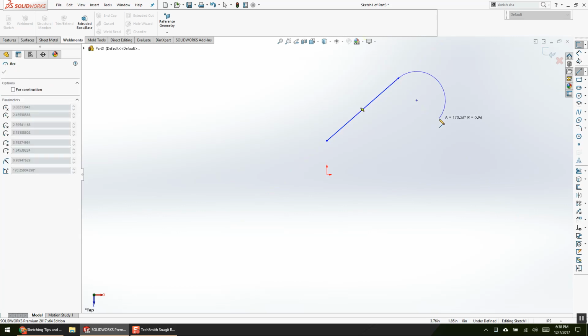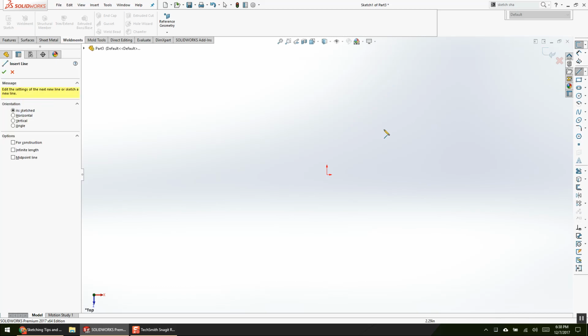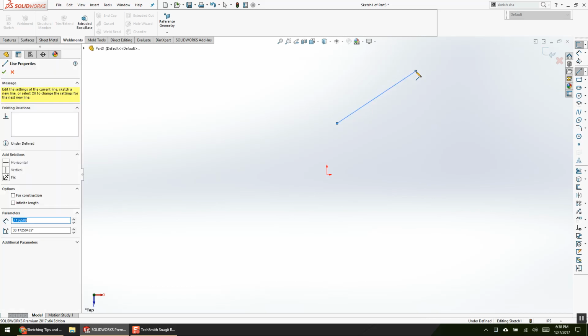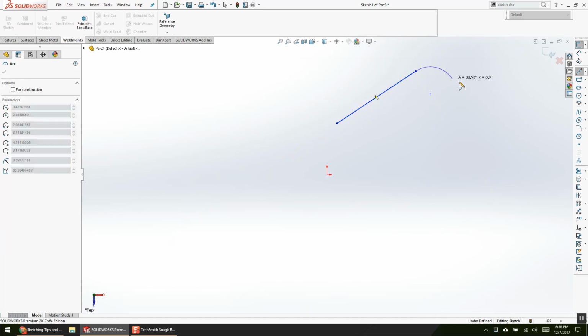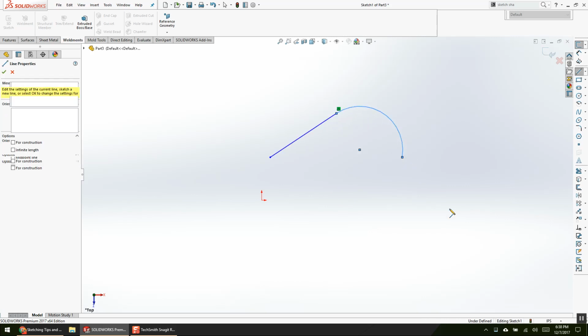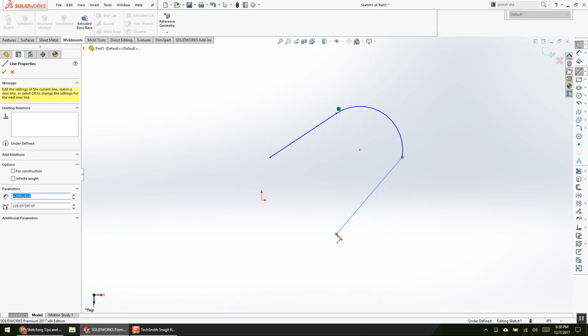And we all know we can draw a line, leave the point, come back, touch the point, and come off as a tangent, right? No? Yeah. Do I need to do that again? All right, I'll do it again. So with your line command, I draw a straight line. You leave the line, come back, touch the line. It'll come off as a tangent in the quadrant in which you left the line. So here's a tangent, an inverted tangent, a right-handed tangent. And so you can make your tangent, click, and then you can keep drawing lines. Or you could tangent off your tangent off your tangent off your tangent.